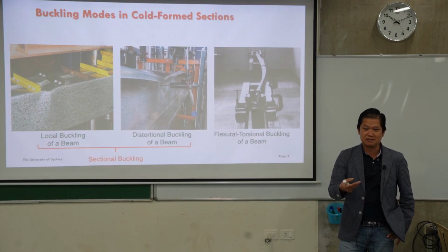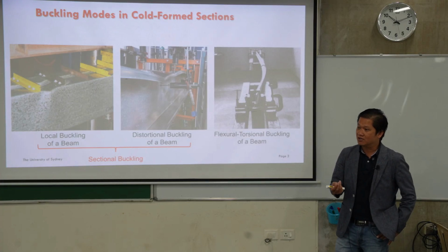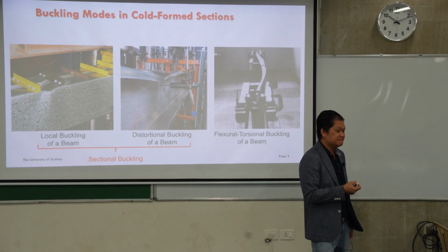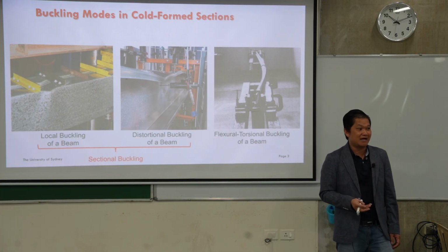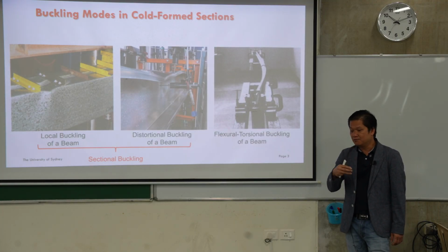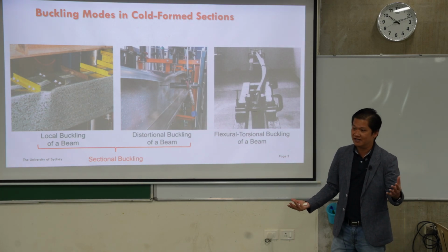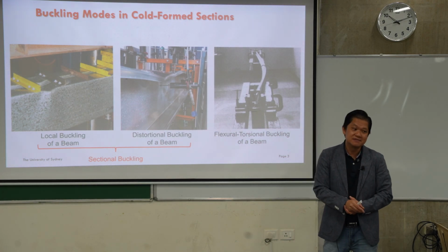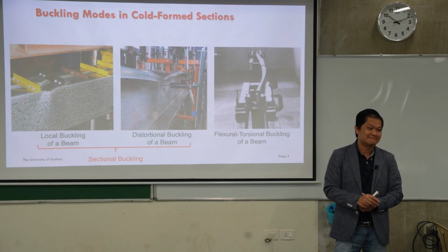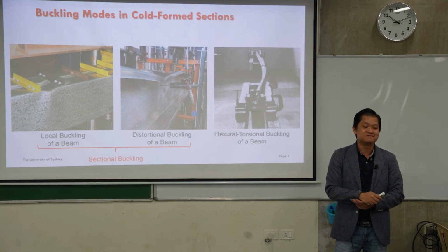The way that BlueScope or the other companies make the coil is high strength steel, G450, G550, which pushes the strength up to 500 megapascal for yield stress. But the negative side is that getting stronger and thinner doesn't help with buckling. That's why it, of course, buckles before it yields.